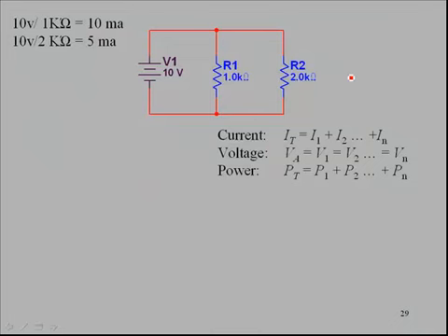Okay, let's go on and do a few more calculations here. We calculated the total resistance. Why don't we throw that in here again, and I'll quickly draw this in. We said our total resistance was 666.66 ohms, and our applied voltage, again 10 volts, that's the equivalent resistance. Now for the current, remember current equals voltage divided by resistance.